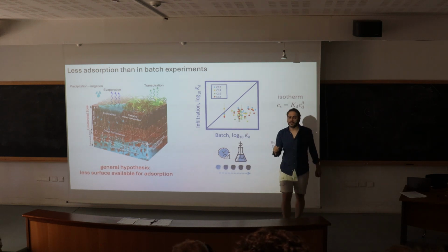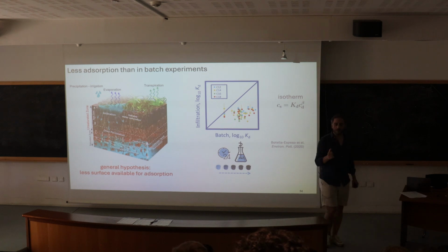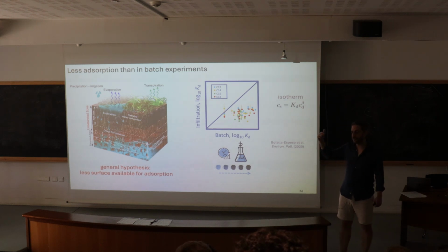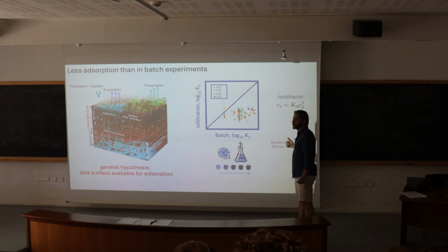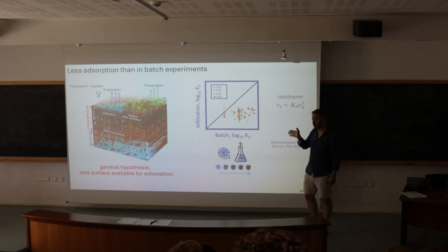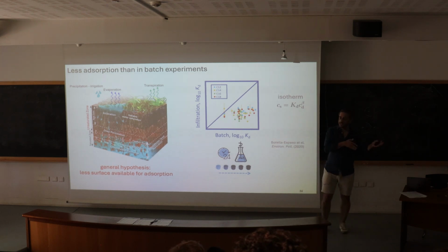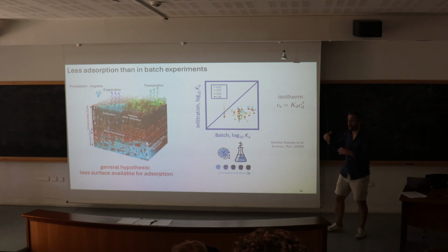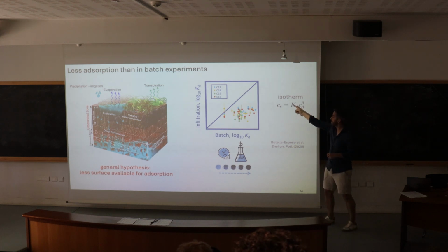You take vessels with different concentrations, you know how much mass you put, and after 24 hours or 48 hours, whatever you decide, you measure what has been the concentration that is remaining in the liquid phase, and like that for different concentrations, you know how much mass has been absorbed. This has to be at constant temperature. That's why this name, isotherm.